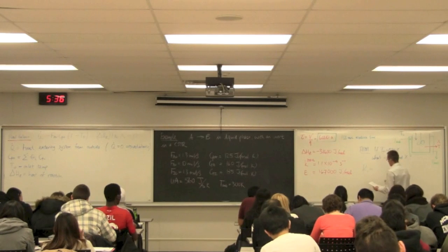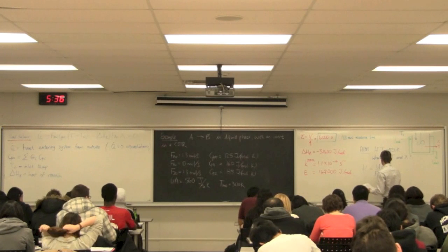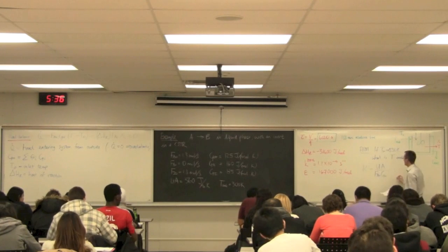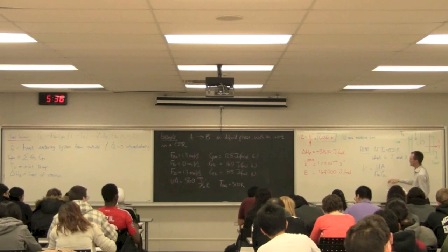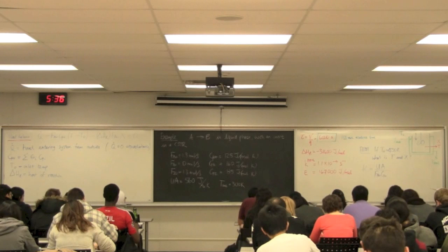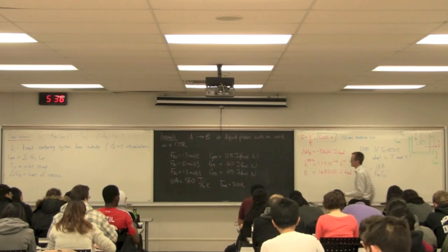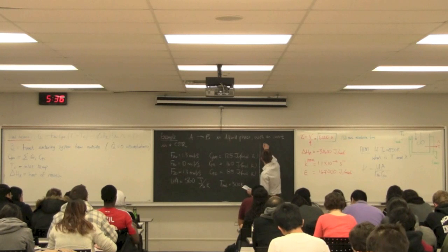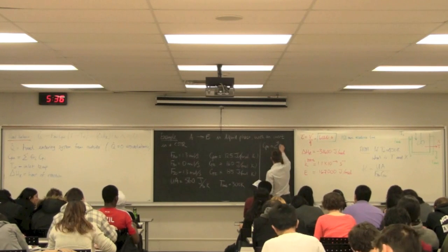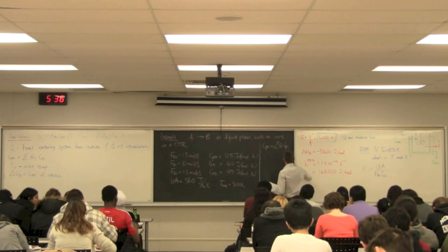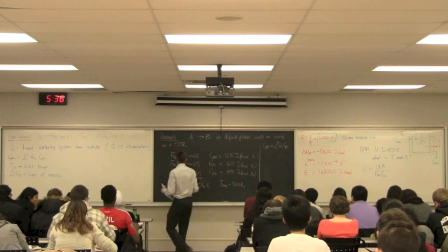It's a dimensionless number that's the product of U times A divided by F_A0 times Cp0. We're given UA, we're given F_A0. Last night we derived that Cp0 was equal to 210 joules per mole Kelvin. Let's just quickly look at that calculation. Cp0 was equal to the sum of theta_i Cp_i. In this case, theta_i is the ratio of the inlet flows.